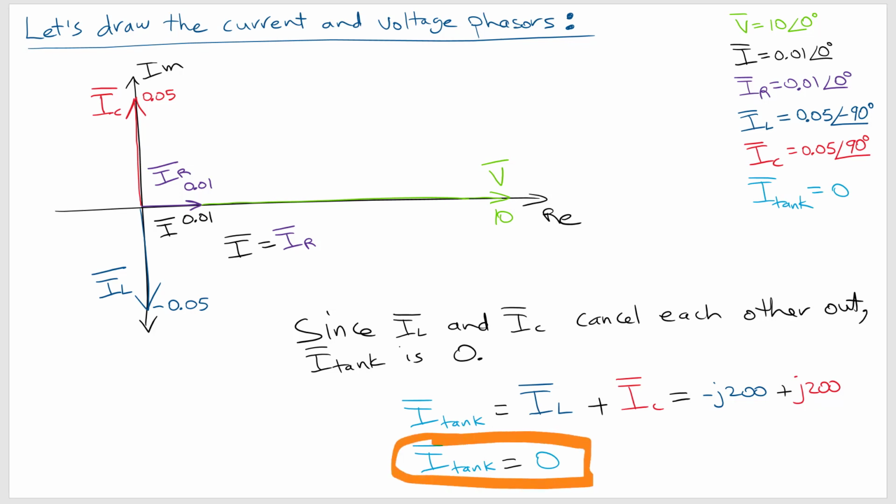Okay, and a little bit later we're going to see what it looks like in terms of a voltage waveform. Okay, we also see that there's a phase relationship between voltage and current for the capacitor. So in a capacitor we have ICE. So current leads voltage in a capacitor. So the current is counterclockwise, okay? So it's 90 degrees leading the voltage, okay? And similarly, we can say that current is lagging the voltage in the inductor, or what we have is ELI. The voltage leads the current in an inductor.